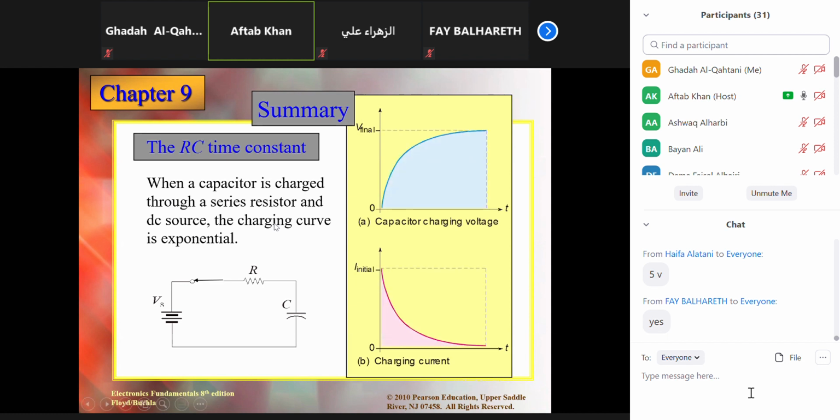As I close the switch, the upper graph is the voltage developed across the capacitor. See, initially the voltage across the capacitor is 0. And as I close it, it allows the current flow. As the current flows, the voltage across it starts building exponentially. See this one. And when it is completely filled, no current will pass. Initially high current was flowing.